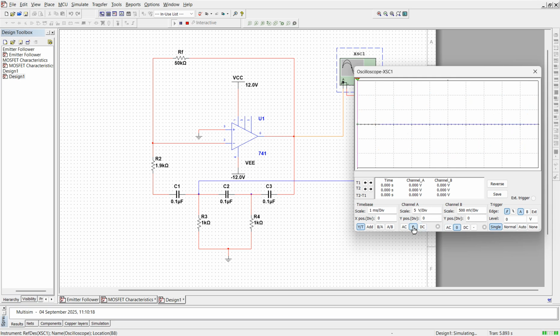Now if I enable the next one, you observe the difference between these two. The difference between these two is approximately 0.6. Right? 0.2, 0.4, 0.6. Approximately it is 0.6. So similar to the calculations we have done earlier, 1.8 divisions is 360 degree, 0.6 equal to how many? That will be approximately 120 degree.